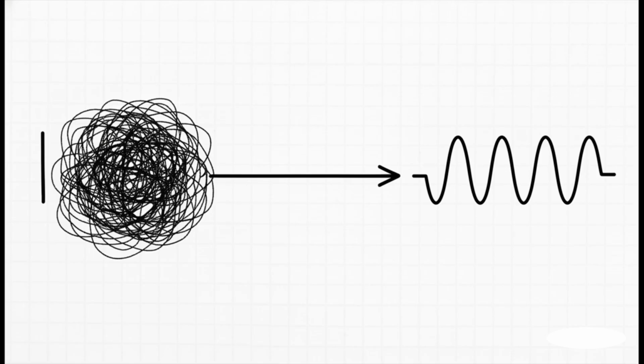But here's where we apply the far zone limit. When we move far away from the antenna, many wavelengths distant, the complex higher-order fractions, like 1 over r squared, drop off to near zero. We are left only with the dominant 1 over r terms. These are the only terms that actually radiate real power into space.